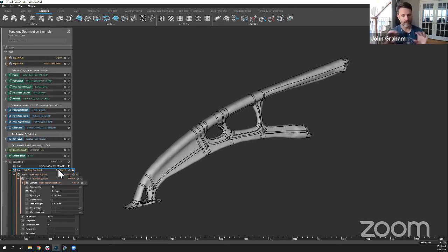So you see these beautiful strips of boundary representation running throughout. One thing I want to draw your attention to is that you can't tell by looking at it. You'd have to go in and do some other calculations and even notice it in a CAD tool, but all of these surfaces are curvature continuous. So you effectively have Class A surfaces, and you're not going to have ripples and strange effects if that's something that you're going for. I think that's just icing on the cake and a little bonus you get when going back to a boundary representation.